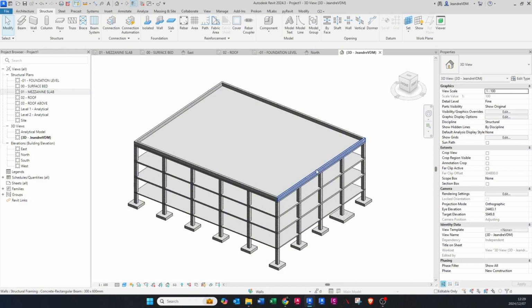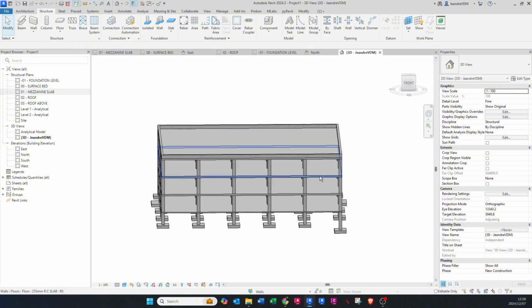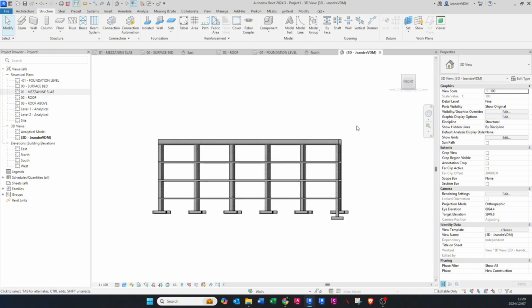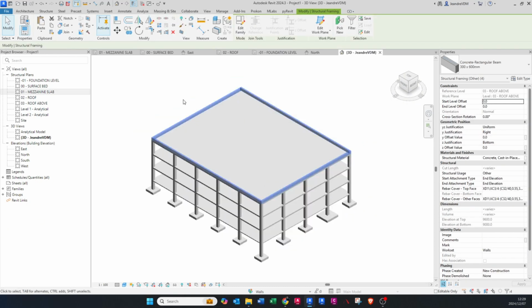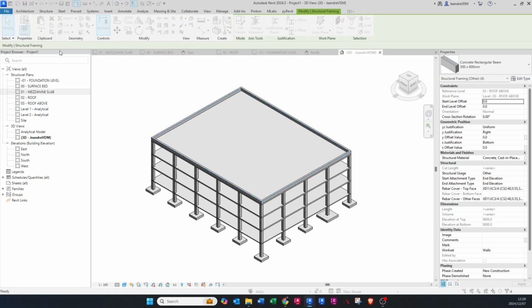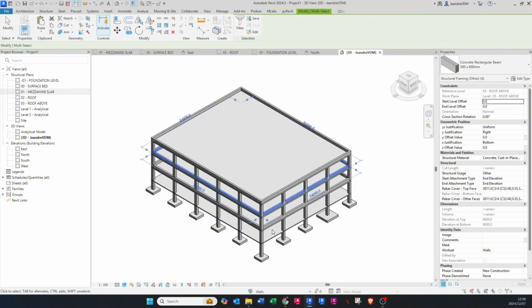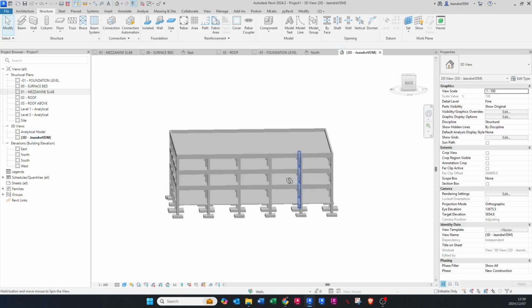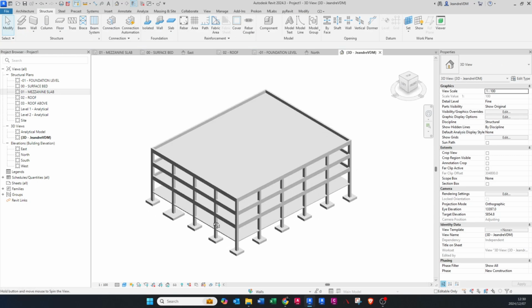Okay, anyway, does not want to work, but the other way you can do it is just rotate in 3D, highlight those beams, and I say copy, say paste, then you say align to selected levels. I choose the roof which is the one below the roof above, and then mezzanine. Say okay. Yeah, I've generated all the beams on the perimeter.